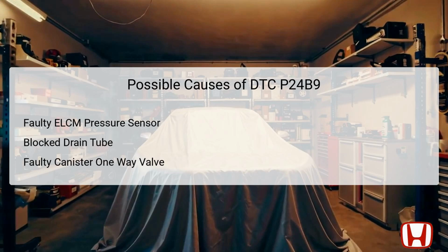Furthermore, if the canister one-way valve is not functioning correctly, it may fail to allow the release of gas vapors, causing pressure imbalances. Each of these factors can contribute to the overall performance issue of the EVAP system, necessitating thorough inspections and diagnostics to pinpoint the specific cause of the DTC.